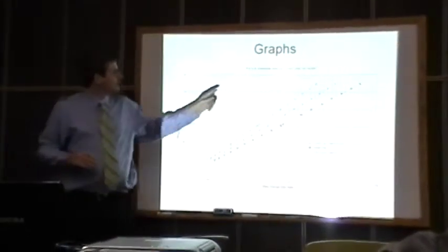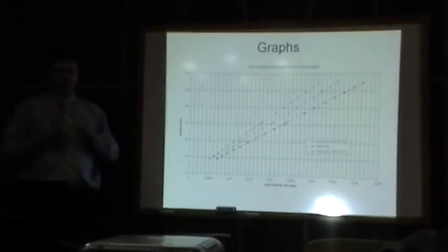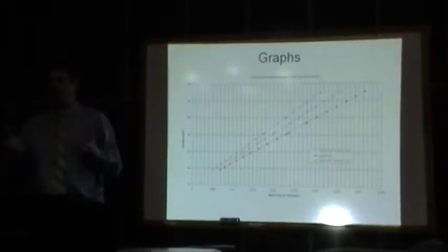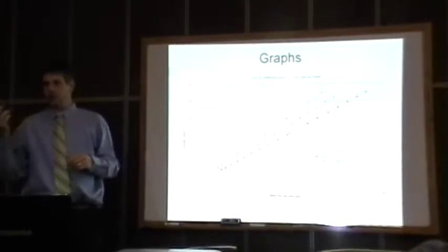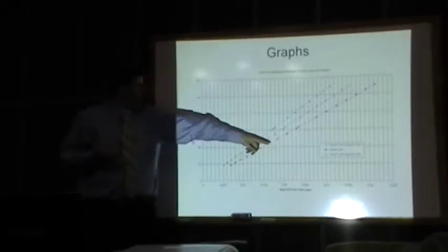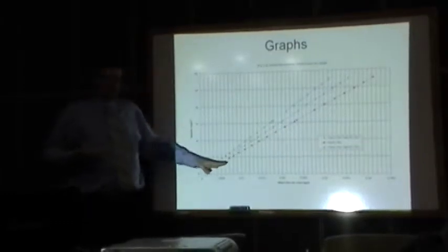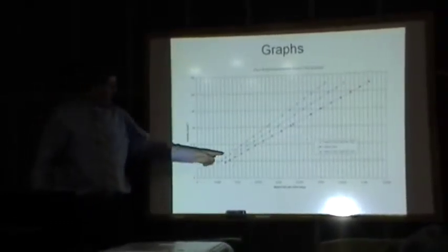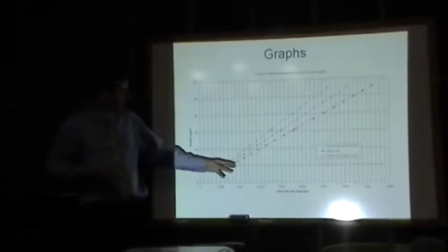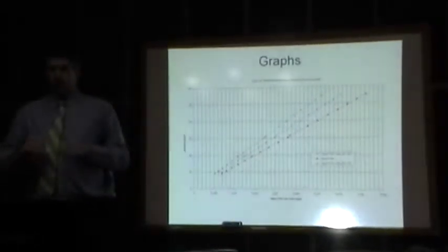Now this is a thrust curve to say how close you can get to a cold gas thruster. Can you just approximate it as a pressure tank that just opens to Mars atmospheric pressure? This was using 2 different Mach numbers for the Fanno flow, and the red line is if you just approximate a nozzle of a single area, and if you notice, they begin to converge. So I believe at a point it is safe to approximate the cold gas jet as if it just exited through a nozzle of no length.